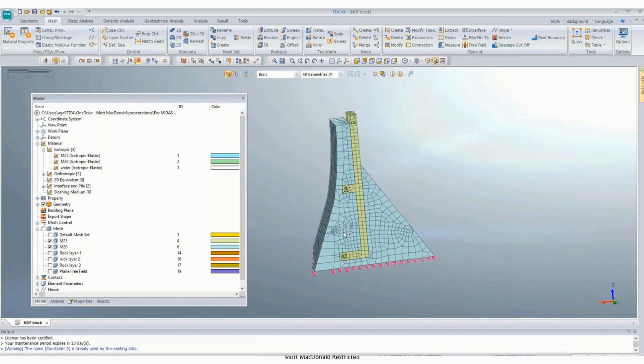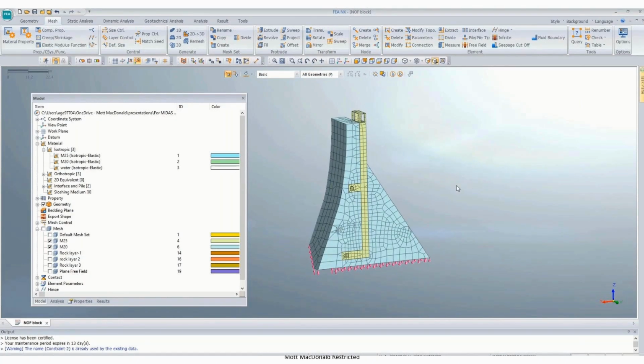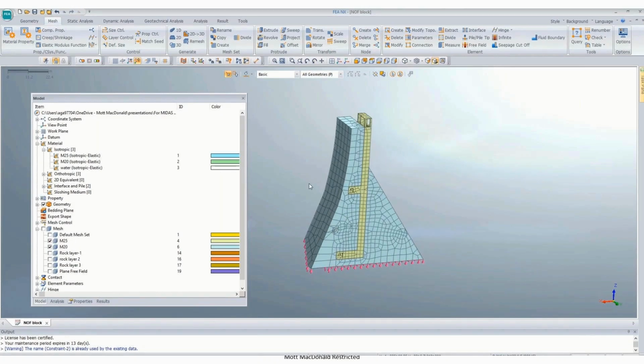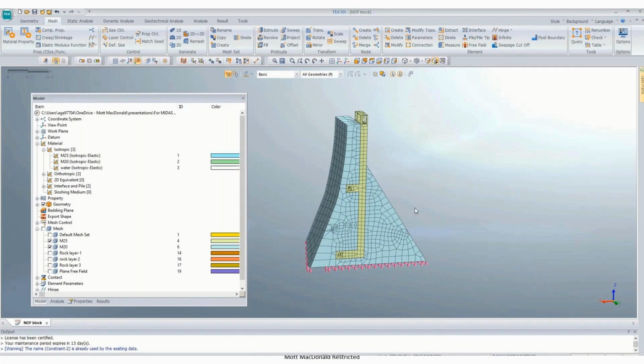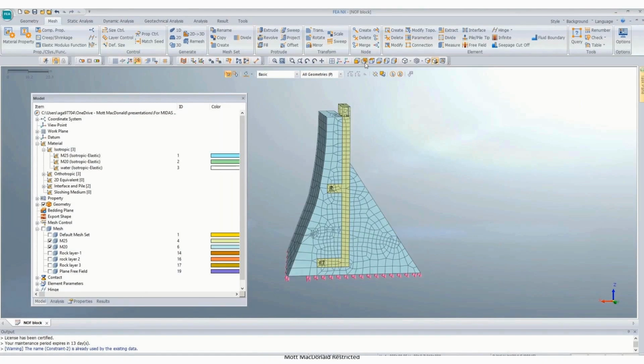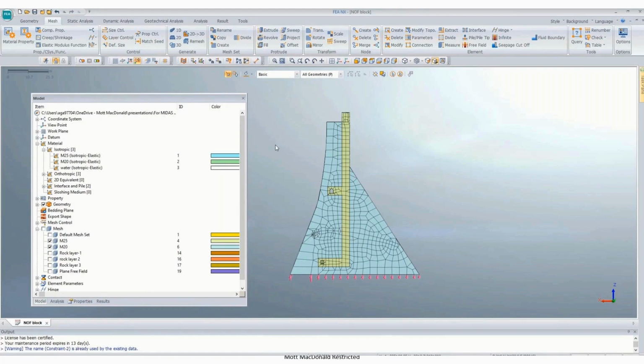And later on, if you refine the mesh and do it again, it will take just 1.5 hours to complete this exercise, I mean, modify the geometry and remesh it. So you will find the stresses are not that apart. Whatever stresses you find here, you will get similar stresses after you have a refined mesh.